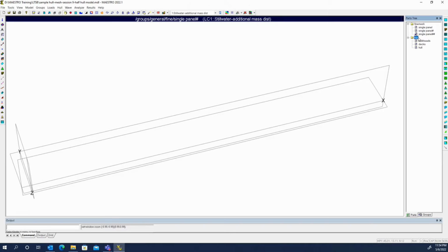In part, that's because when you go to do your runs, we can run when we analyze. Typically, we'll do the global and local FEA, but if your model does contain a fine mesh model, or more specifically, if you have a lot of fine mesh models in there, which would slow down your runtime, you may want to solve the global FEA model separately to see if things are working as expected on a global scale, make sure everything passes whatever checks are needed.